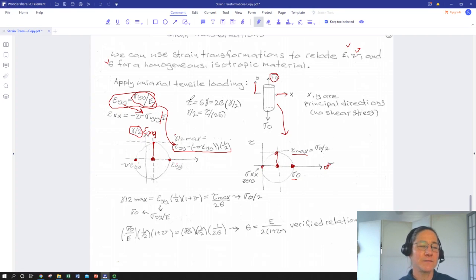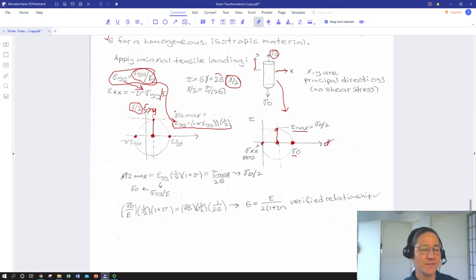Then we can relate shear stress to shear modulus times shear strain. That's engineering shear strain. We can do some math magic and pull a 2 out, and then have our tensor shear strain here, which we can then relate to something on our Mohr circle, on our shear strain Mohr circle. Rearrange a little bit. Now we can just collect terms.